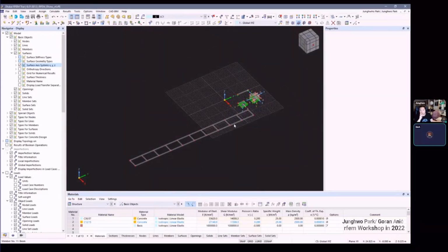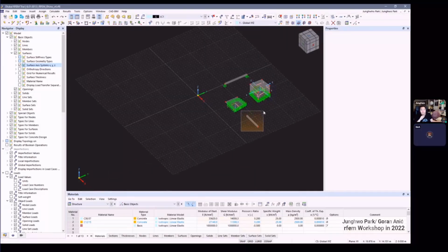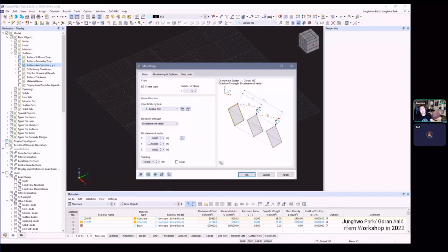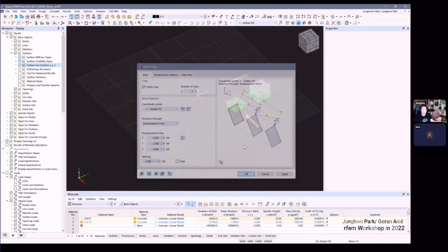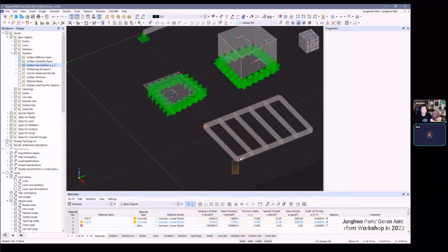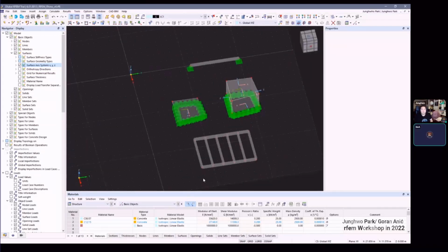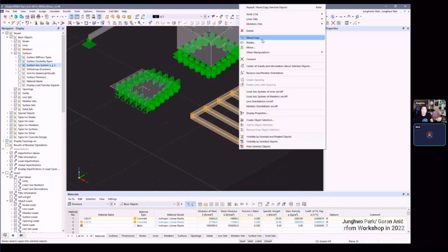Okay, 2 times and just second. This is the part I want to get, and I will choose all my nodes and put just a regular spring support under, because I want to put some load on this.